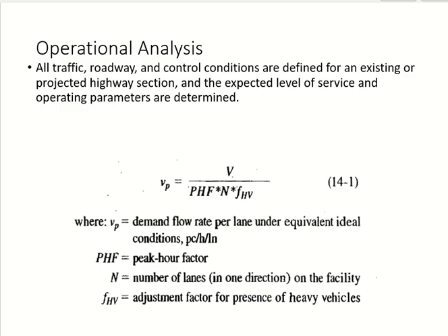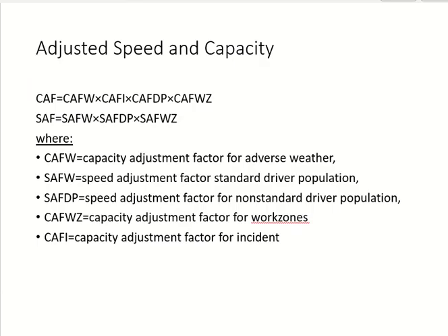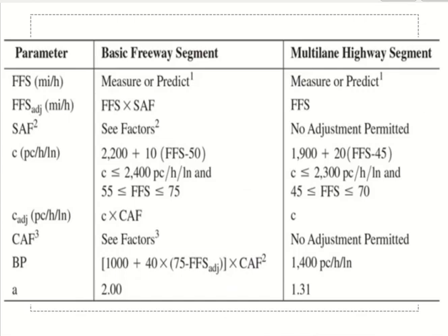So I need to calculate density for the level of service. For density, I must decide about this speed. For speed, I need to check if I am in the free flow condition or not. For that, we have to take the breakpoint.